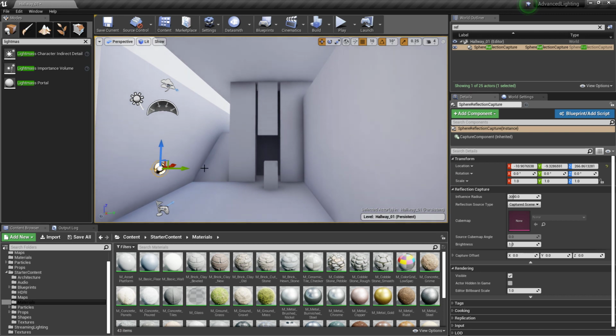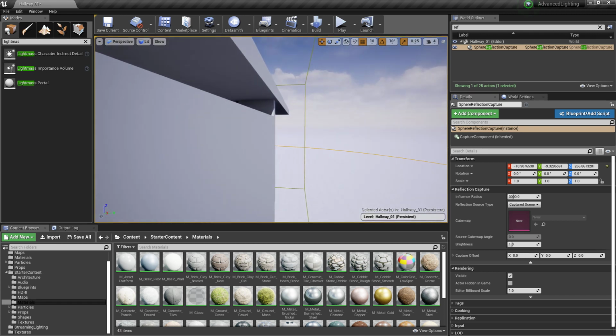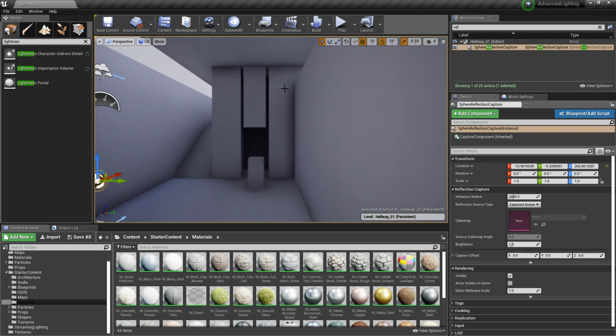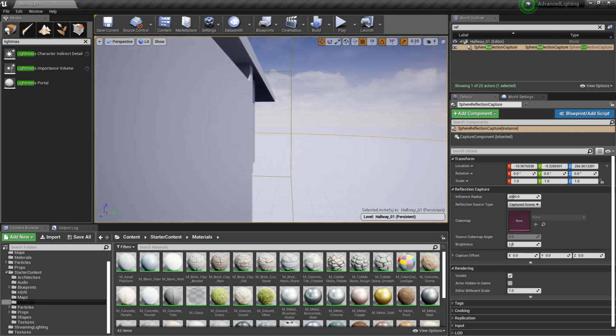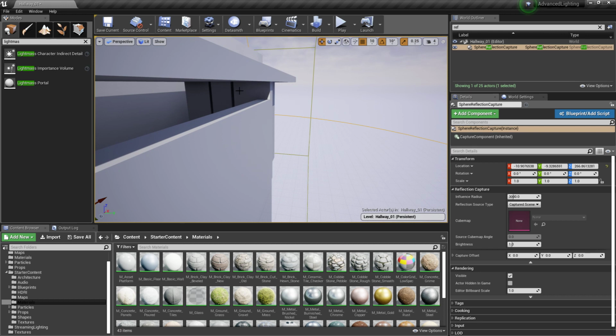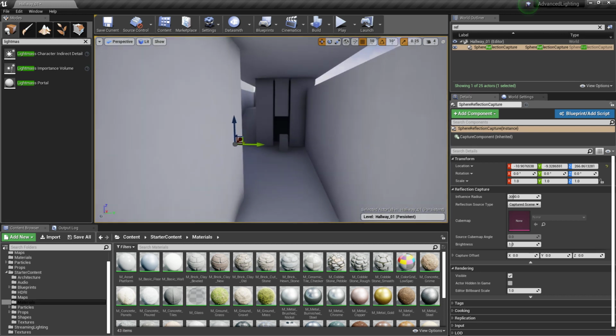You notice we got much better quality shadows going on now. We've also fixed that egregious shadowing difference from outside to inside. Again, like kind of how I told you, be careful with meshes that hang out too far, especially if the lighting is way different. Super bright out here and dark inside there.